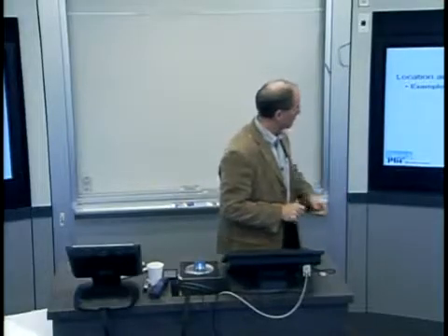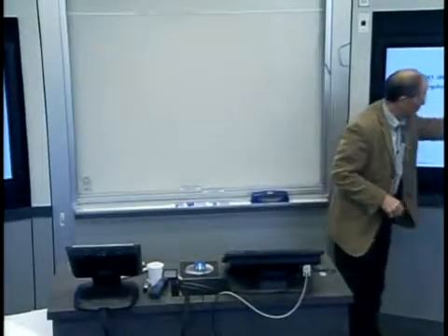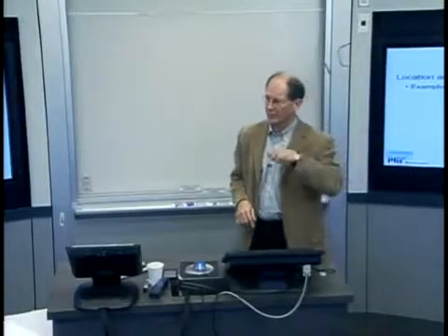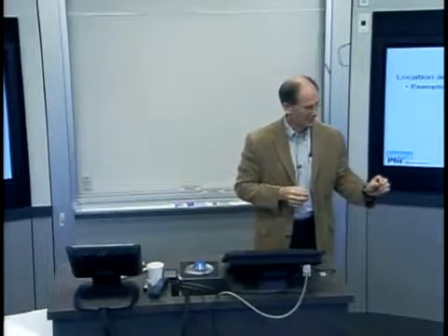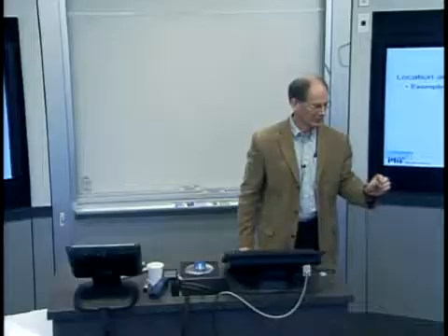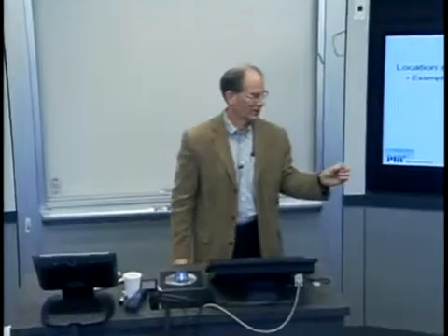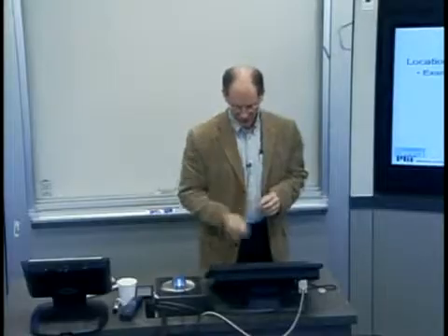This is meant to be a picture of a robot moving it around. So the robot is very important in this case because it's providing the motion and moving the laser tool. And of course, this has been taken to extreme with femtosecond lasers, which at any given instant will only ablate material in, I don't know what, submicron areas. So you can really localize it if you want to.